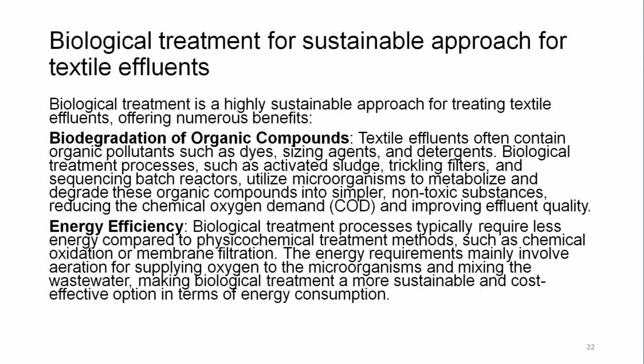The energy requirement mainly involves aeration for supply of oxygen into the water body for the microorganisms and mixing the wastewater, making biological treatment a more sustainable and cost effective option in terms of energy consumption. So, even in the biological system, the energy consumption is very regulated, it is not intensive.